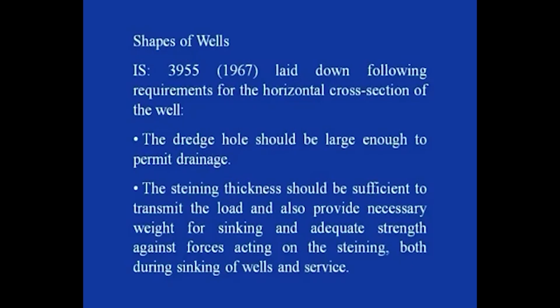Now the thickness of the steining is also one of the governing factors as far as the shape of the well is concerned. The steining thickness should be sufficient to transmit the load and also provide the necessary weight for sinking and adequate strength against forces acting on the steining both during the sinking of the well and in service. As I mentioned when we were discussing the components of the well and well steining, the thickness of the well steining is an important aspect as far as the design and analysis of the well is concerned.